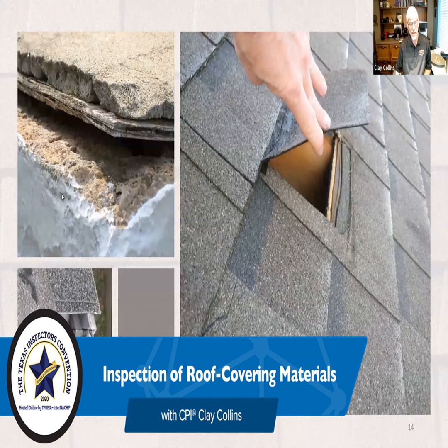I think you're not going to see this unless you're doing framing inspections or inspections where you can see it before the installation of the roof cover, the underlayment, the roof cover. If you try to look at that from the attic space, the butt joints should terminate over a rafter. And if it doesn't, you've got a bigger problem, and you should be able to identify that pretty quickly.